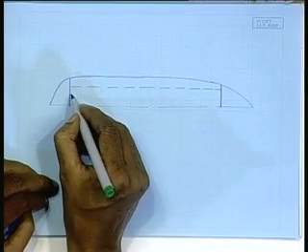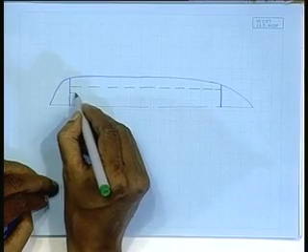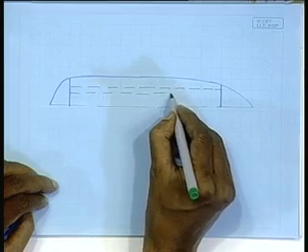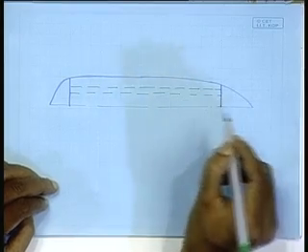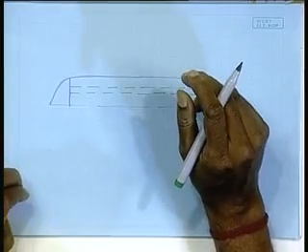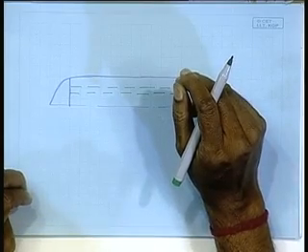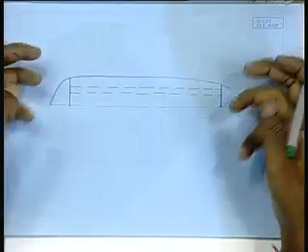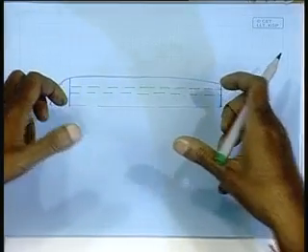If the same deck I would have provided transverse stiffening arrangement, then the weight of the deck would have been more, or strength to weight ratio of the deck would have been poorer, had this deck been stiffened transversely. Why? Because by providing transverse stiffening, I will have to take care of the longitudinal bending, and that longitudinal bending may cause buckling.